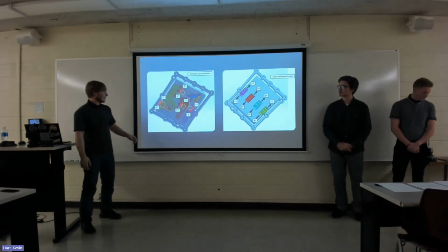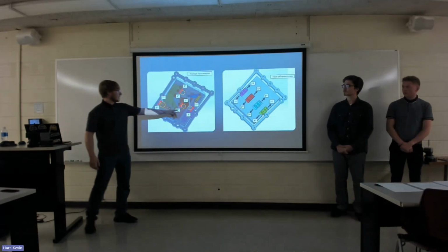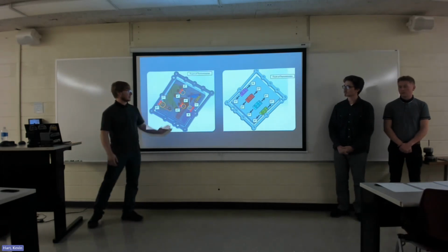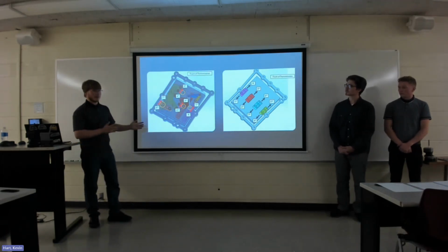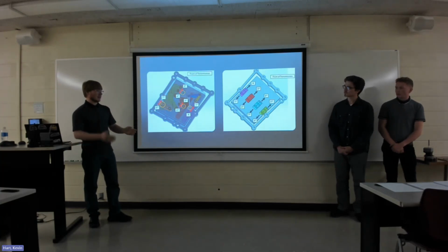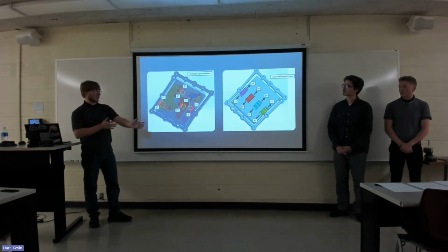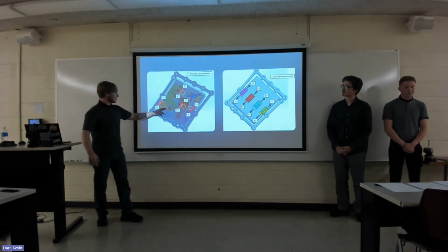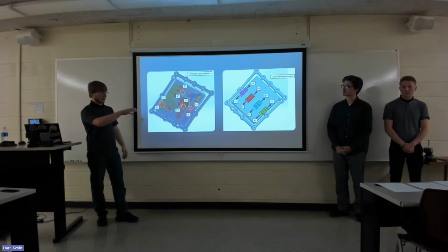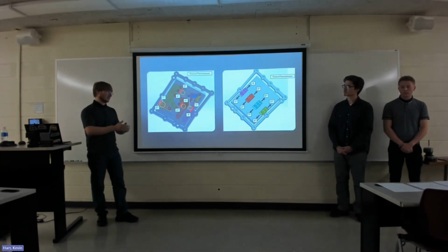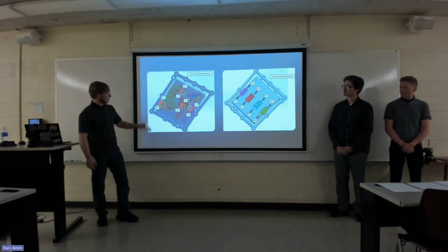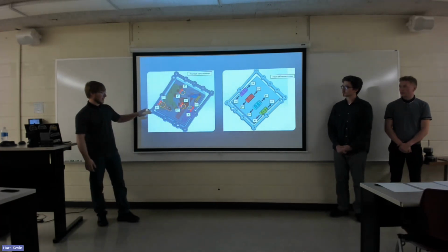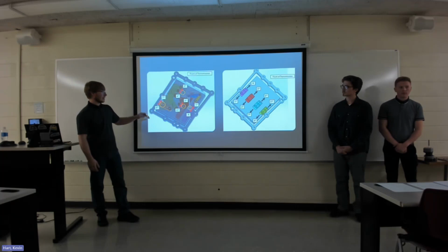So now I'll talk about the sub-mechanisms a little bit. Circled in yellow are the inputs to our transmission mechanism. Now these all translate along the long axis of the transmission, which is parallel to the transmission tunnel. We have a pin on each one of our sub-mechanisms that will interface with an input linkage, which is to be designed next semester. Each one of these is in line to line up with the outputs of the driver interface mechanism, so we won't have any crossover in our connecting linkages.